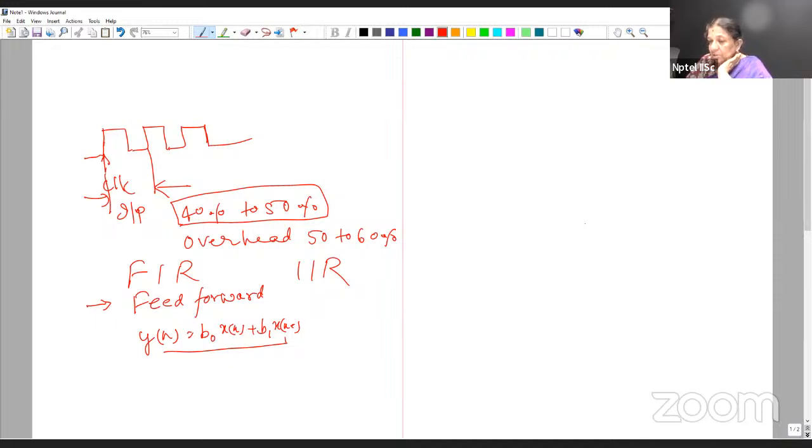Based on how you look at your algorithm, if the input and output are reversed, then the delay elements can be ordered differently. From the architecture point of view, which was going to consume one multiplier and two adders, we can bring it down to one multiplier and one adder. So our hardware is also going to be reduced, and our output is not going to change.